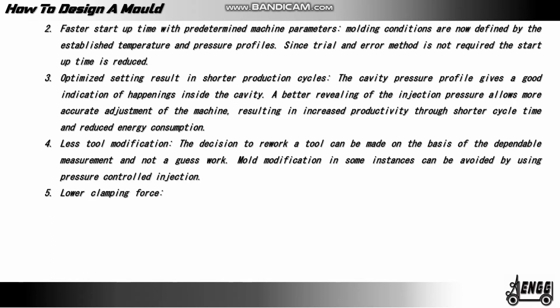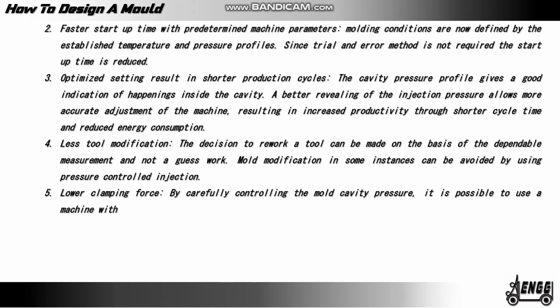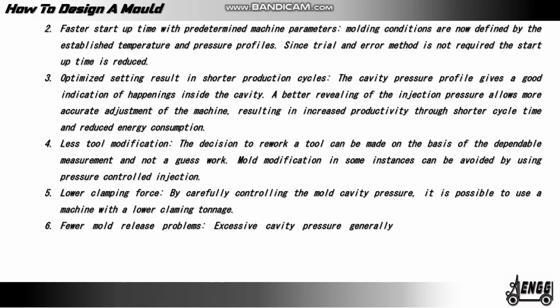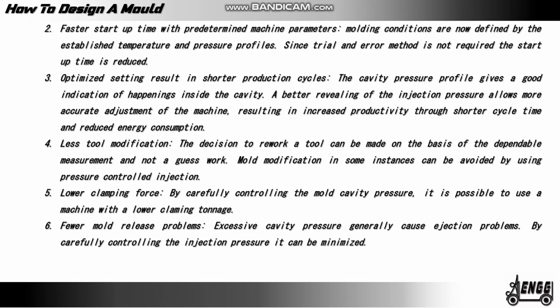Lower clamping force. By carefully controlling the mold cavity pressure, it is possible to use a machine with a lower clamping tonnage. Fewer mold release problems. Excessive cavity pressure generally causes ejection problems. By carefully controlling the injection pressure, it can be minimized.